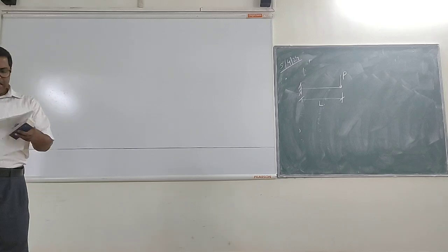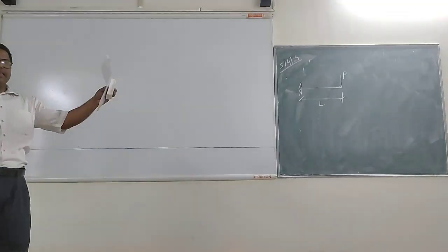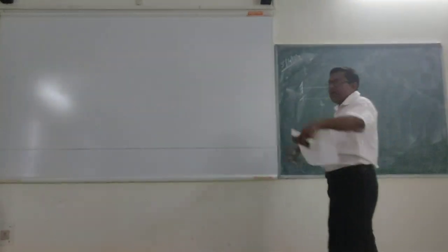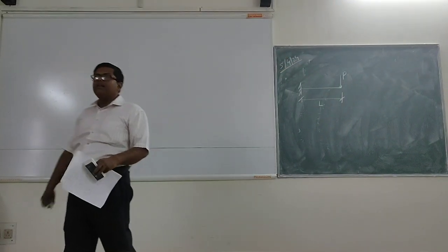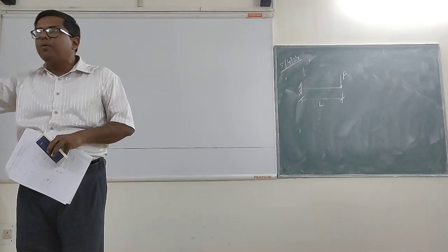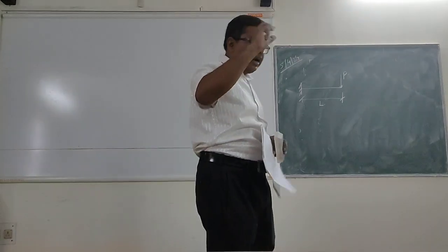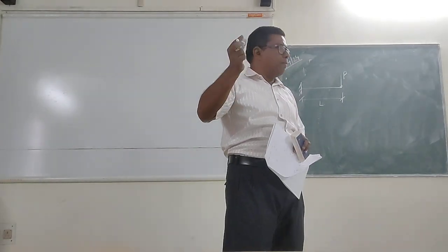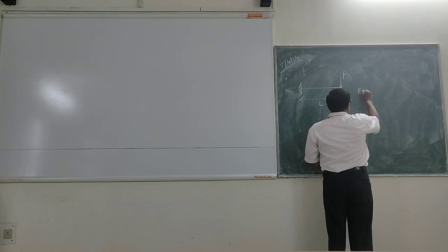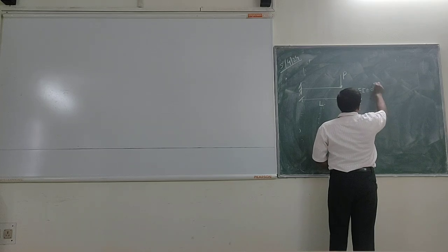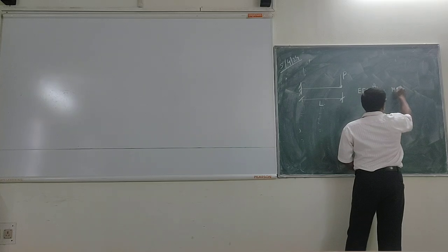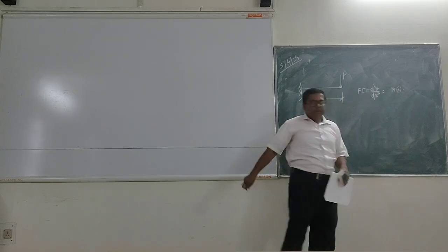Now you see there will be two different cases of bending moments. One is sagging, one is hogging, right? So depending on the hogging and sagging, you can take the value of your moment. In case of a cantilever, generally we term it as a negative bending moment, right? So negative bending moment, minus PL. So now what is my equation for solving using double integration method? EI d2y by dx2 is equal to what? M of x, something like this, right?